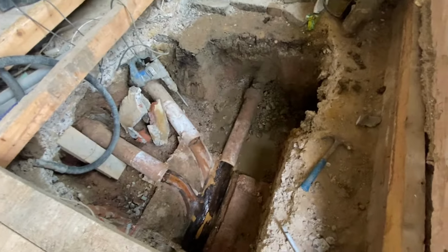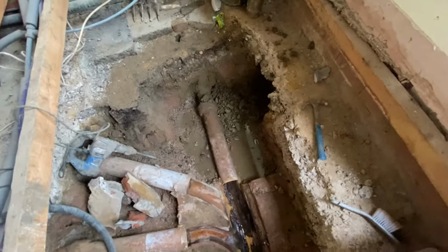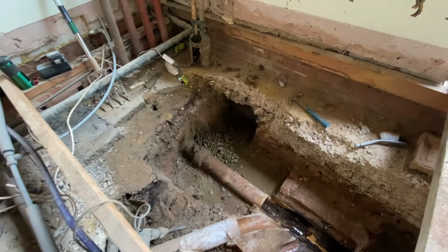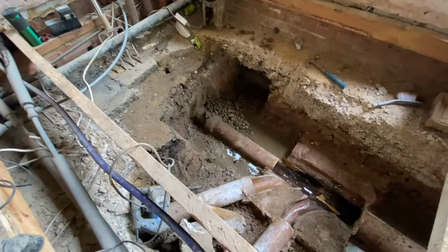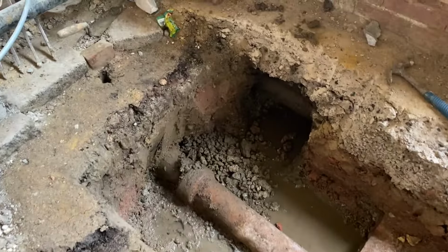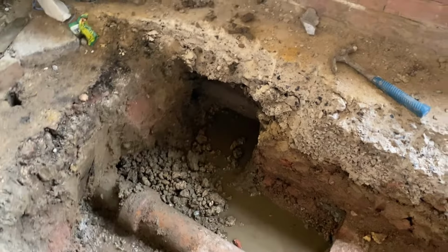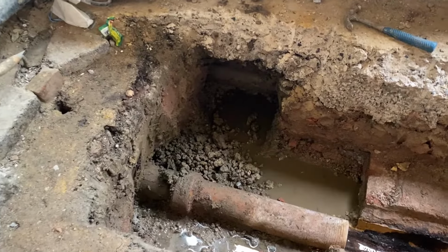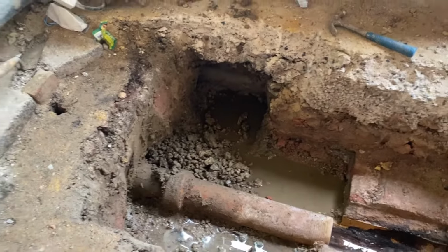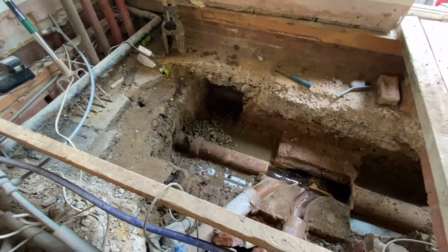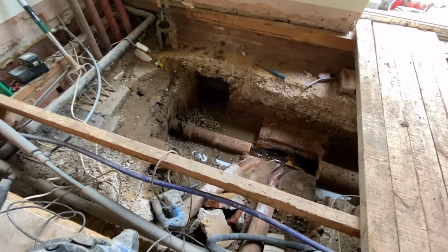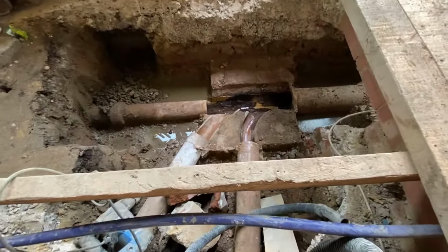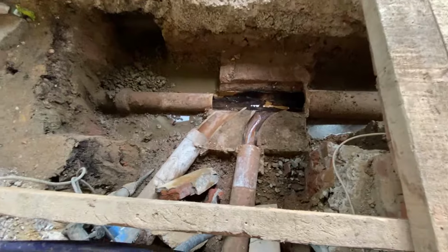We're basically going to replace these pipes, and you'll see at the end of the video exactly what we do. But this arrangement will stay in place for the existing house and the existing sewer. And all we're doing here really is adding an access rodding point under this portion here where we can see we've been digging under the wall. So that's the main objective here, is to break through this wall, dig down that channel that we're digging outside to be able to lay a pipe to access this sewer and be able to rod and clear any blockages in the future.